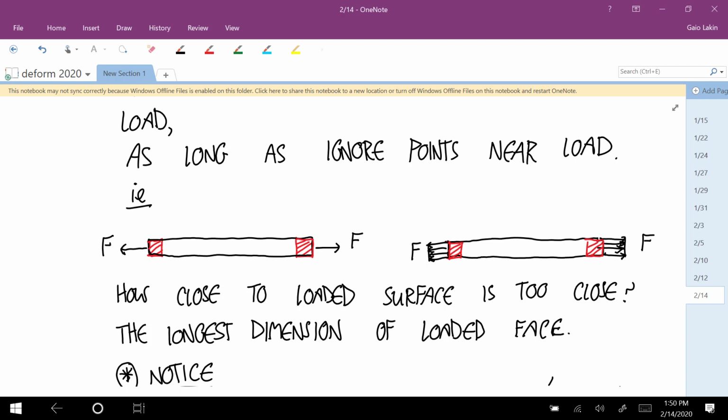If you have a pure compression fracture of, say, a bone, but it happens in other brittle materials too, what you see always is that, like in car accidents, people's feet hit the front by the pedals, they get compression fractures in their legs. What that looks like is a fracture at 45 degrees, like this, because brittle materials are very bad at handling shear stresses. And so it fails in shear. And if it's going to fail because of shear stresses, it's going to happen on that first face where the shear stress is big enough, and that's at that 45 degrees.